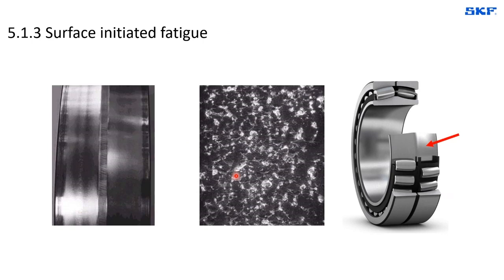Some people will also call this surface distress or micro-pitting. And the reason for this is usually related to a poor lubrication condition, which basically increases the surface friction, and that basically leads to these small cracks and micro-spalling to form.